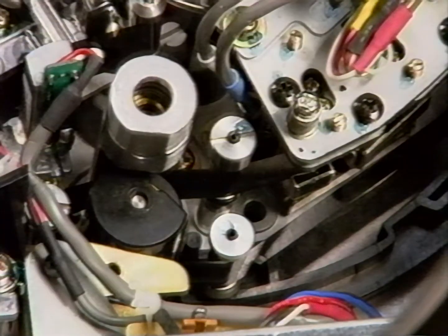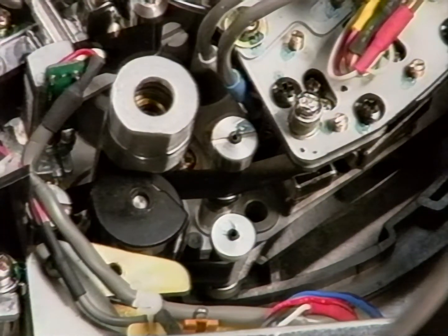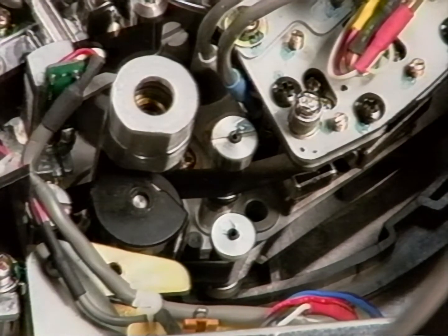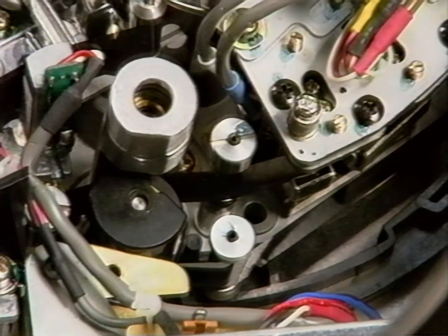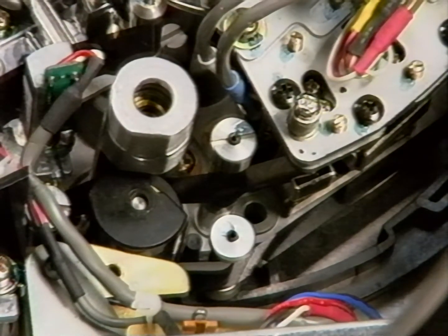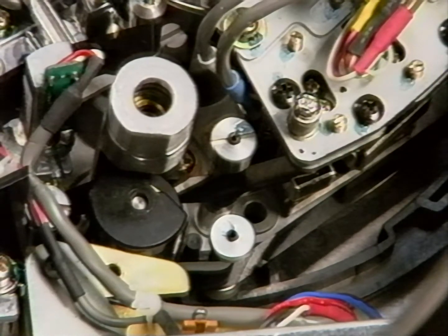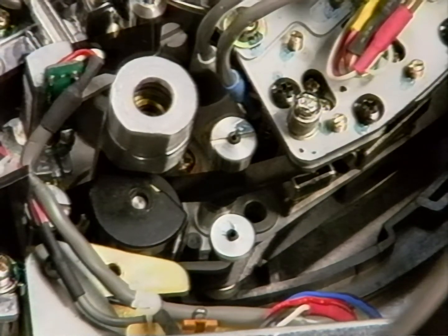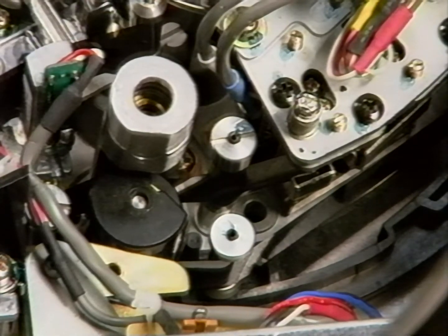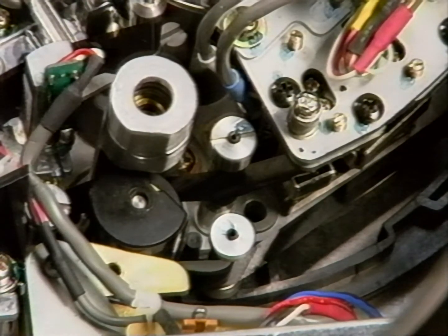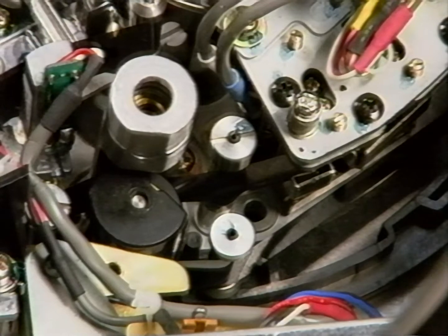Pinch roller. Here we see a worn pinch roller operating in the play mode. In normal play, a worn pinch roller is not always noticeable. However, when we shuttle the tape back and forth in the DT mode, the tape disturbance is apparent. The tape wrinkles as it rides up and down at TG4 and guide C as it is shuttled back and forth.